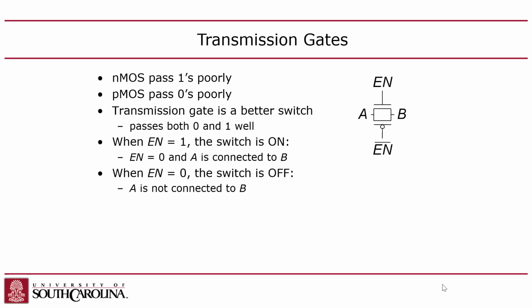And then we talked about transmission gates, which are used for tri-state buffers. A transmission gate is a way to electrically disconnect two terminals. So we have an A terminal and a B terminal, and we want to be able to either connect them or disconnect them. In that case, you'd use a PMOS and an NMOS in parallel, because the PMOS is designed to carry a 1 across these terminals, and the NMOS is designed to carry the 0 across the terminals. Sorry, I had that reversed earlier: the PMOS carries the 1 and the NMOS carries the 0.